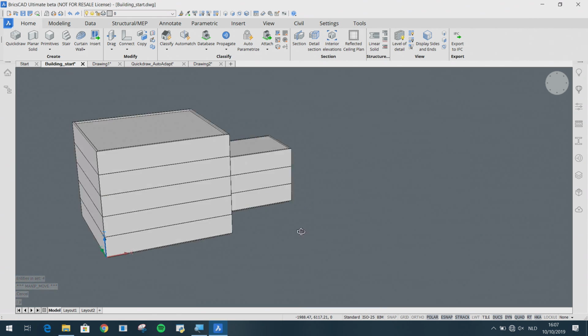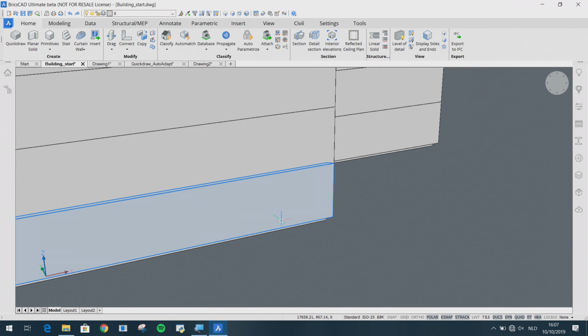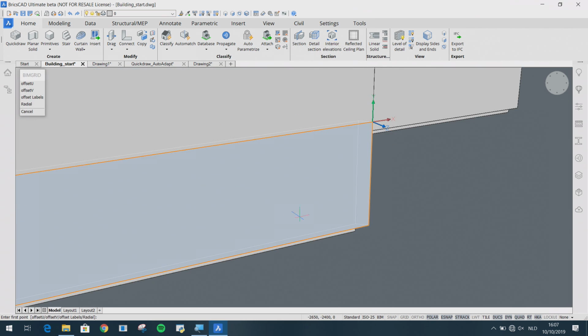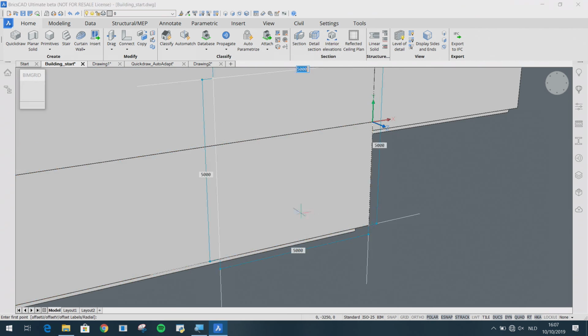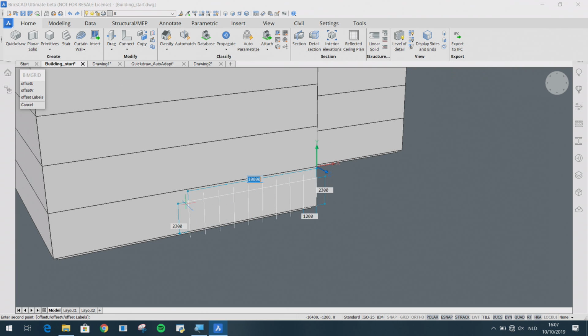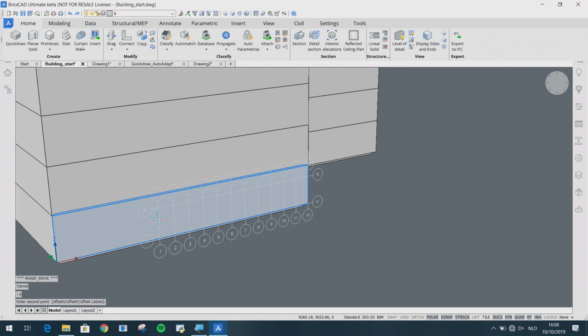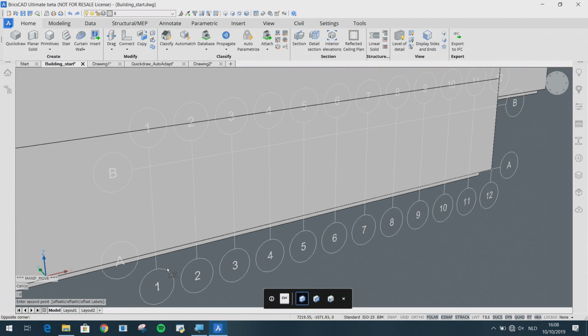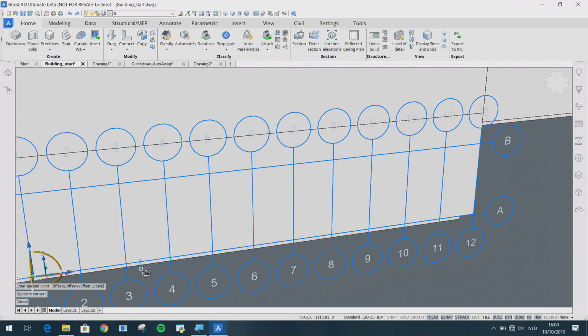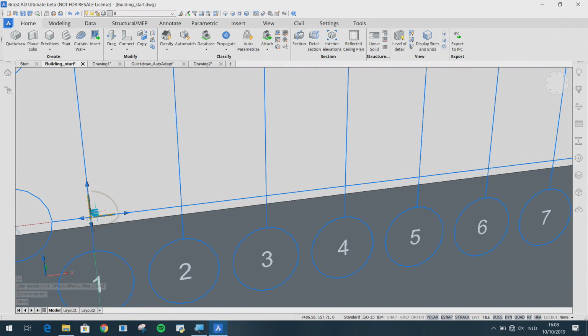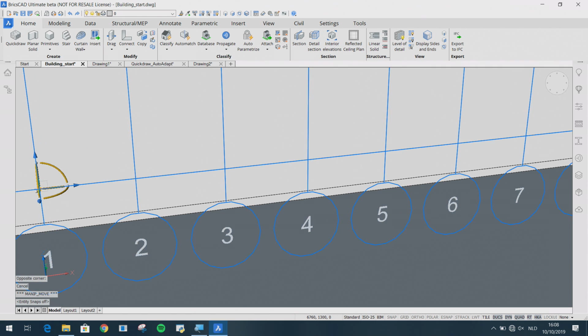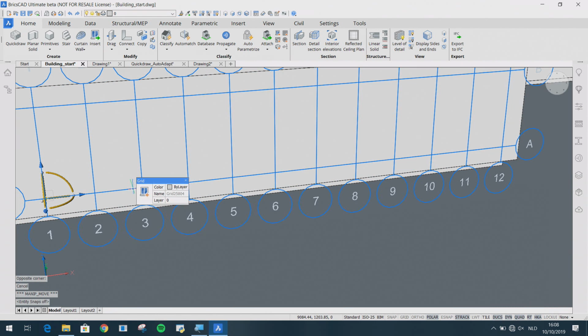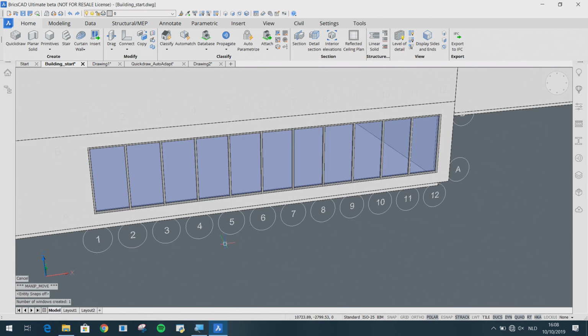But of course, conceptual design involves more than just the form of the building. We also want to add glazing early on in the design. And Wouter will now introduce some windows using the Window Create tool in combination with the BIM Grid tool. So he's just drawing a grid on one of the walls, loosely positioning it. It's not very important where it is at this stage. We can then just select it and call Window Create from there.